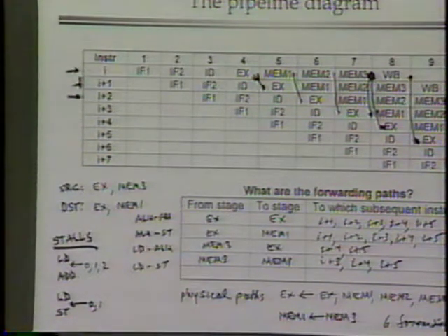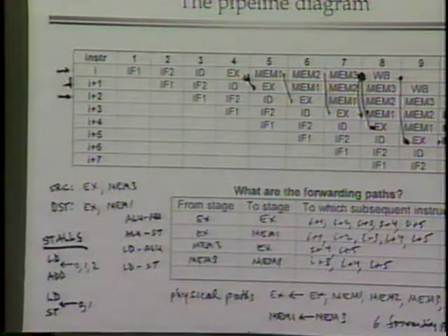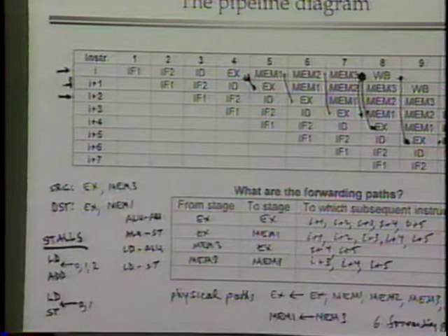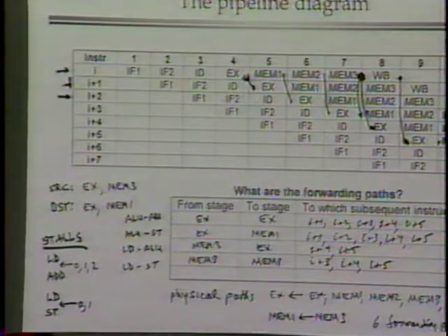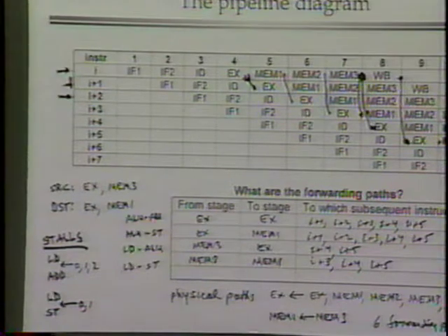So if you have an instruction in your instruction set that might compute an address and then store data, is it possible to have to use the same forwarding path twice when you're combining these physical ones? Once you need to go down to the execute stage to compute the address, and the other you need to go down to the execute stage to put the contents of what you want to write. Yes, I could see that in a sufficiently complicated instruction set, you may need to do that. So you might need two separate paths, or choose an alternate path rather than one of the paths.